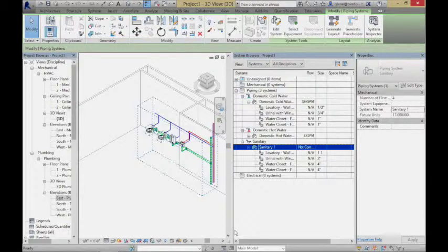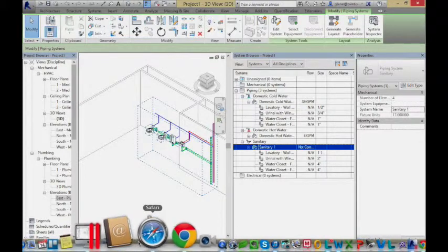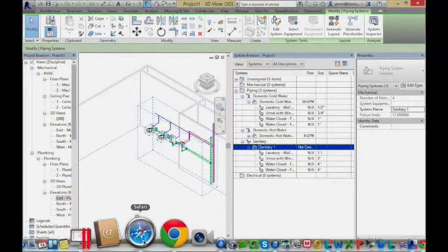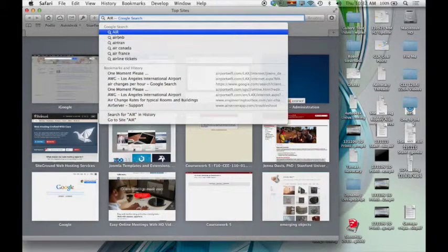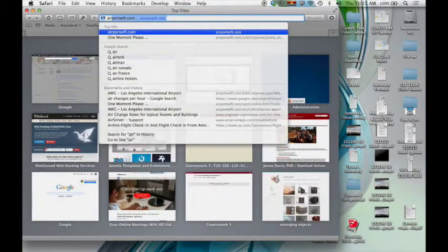Another major consideration that you don't think about as being one of the big drivers is the ventilation side, just the freshness of the air in the room. Every room, depending on its use, has a certain requirement for how much fresh air you have to be introducing all the time. And honestly, that's probably the bigger driving consideration of how these types of systems are designed.